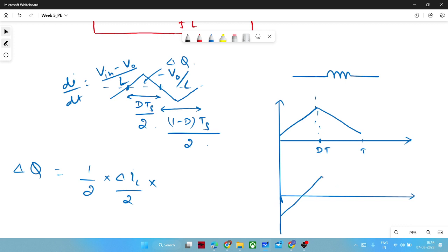That's what we are assuming, like we assume the inductor voltage to be zero average. In the same way, the ampere second relationship for the capacitor, or the average current flowing through the capacitor, is zero. That's what we are trying to say, right?